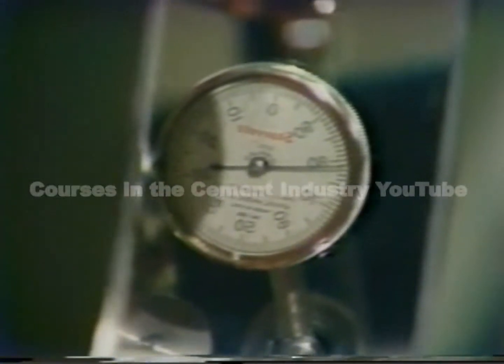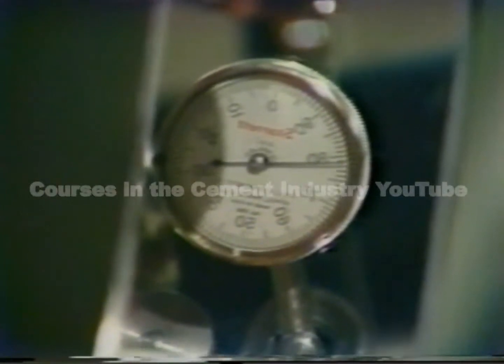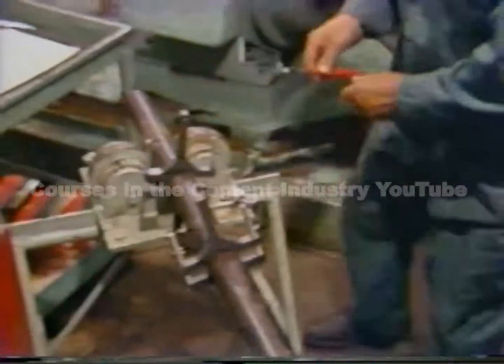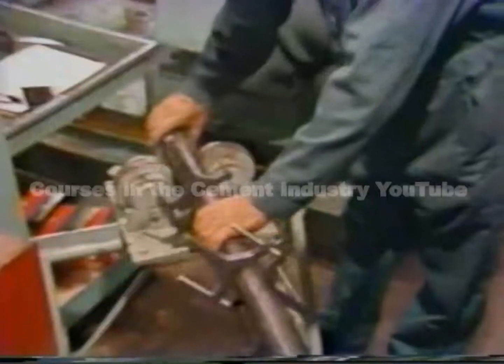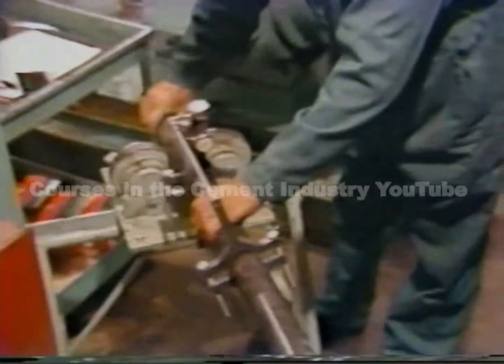Sag should be read at maximum deflection and will always be a negative number. So the technician knows that 21 thousandths on the offset dial must be accounted for as sag and not misalignment.